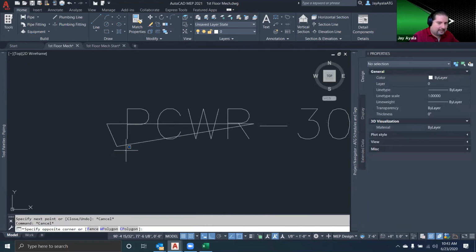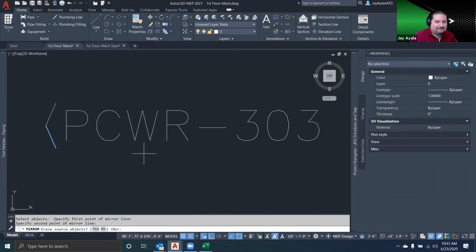Okay, perfect. Now I'll get rid of the miscellaneous line work. I'll mirror this, mirror. I always have trouble with that word. Okay, and mirror this one more time. INS. There we go. And now I'll just close this up with my line work.